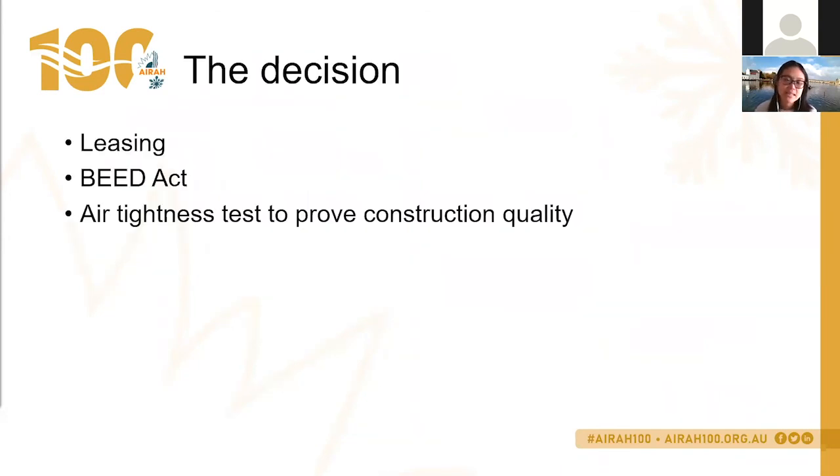So ultimately, the decision of your client whether they should be using a verification method, and which verification method, depends on what their leasing arrangements are. If they see value in perhaps using a NABERS rating or Green Star rating to advertise for tenants, then there's definitely value in going through with JV1 and JV2, because you're already spending all that money and ready to take it through to operation, with all the requirements surrounding a NABERS commitment agreement and a Green Star design and as-built rating.